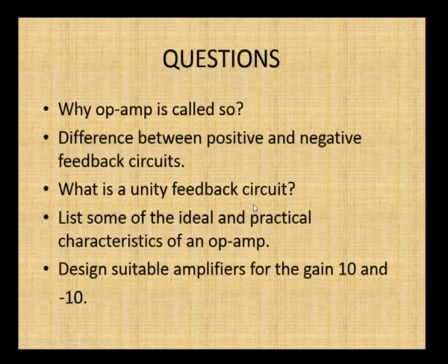What is a unity feedback circuit? Just now we have discussed. It is a voltage follower circuit. In the voltage follower circuit, the output is the same as the input. V out is equal to V in, so the gain is 1. So it is a unity gain feedback circuit.